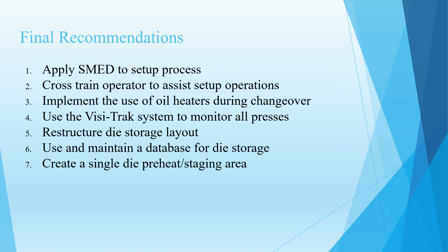Implementing oil heaters for an external die preheat is the most important step they can take to implementing SMED. Using an alignment jig will improve consistency in die mounting. We recommend that Cast-Rite implement a process monitor to all of their machines simultaneously in order to maintain process control. Restructuring their die storage layout will allow them to retrieve dies more reliably and quickly. Using and maintaining a database will allow any employee to locate dies easily.